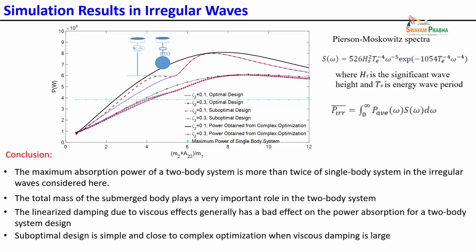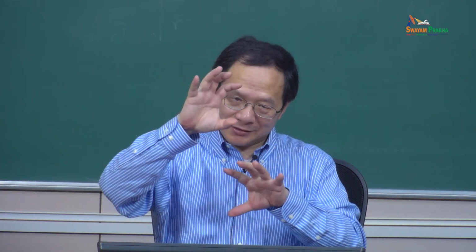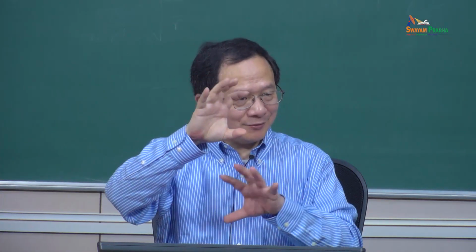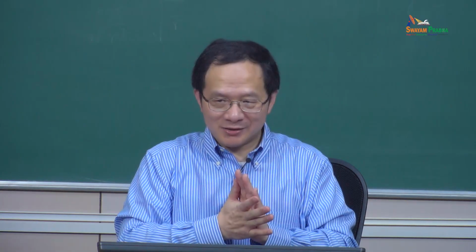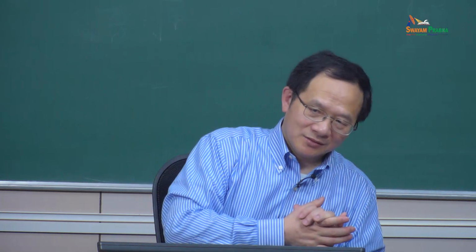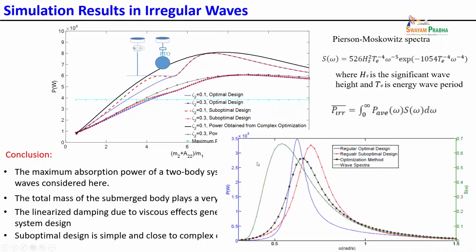And the key insight is not just numerical optimization. You look at the eigenvalue, look into the natural frequency, and it turns out that in this case you match the excitation frequency with one of the damped natural frequencies, one, because you have two natural frequencies. So I want to show you this result.